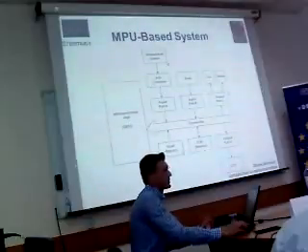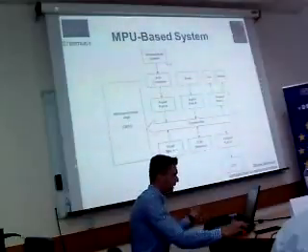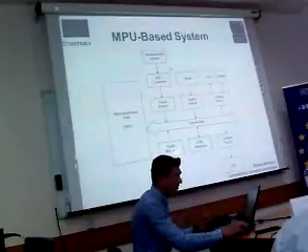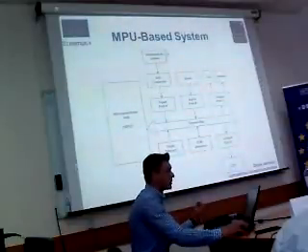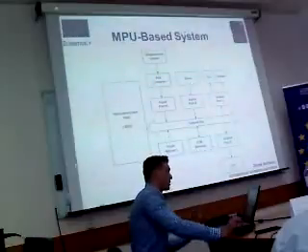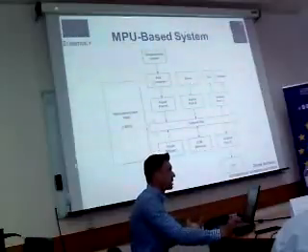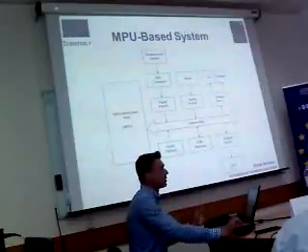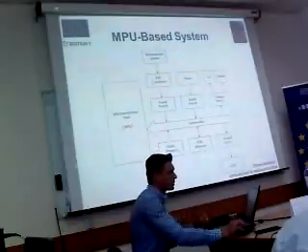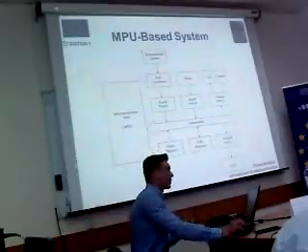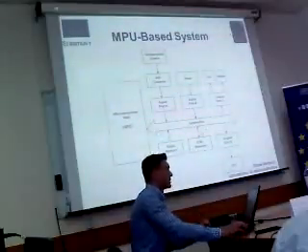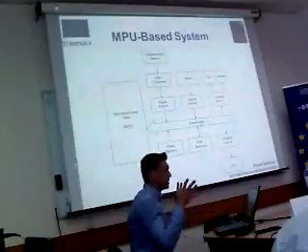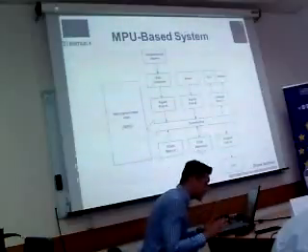What a temperature sensor does, you know, yeah? It measures the temperature, and this temperature is translated to an analog voltage change. So the higher the temperature, the higher the voltage, for example. Then this analog voltage signal goes to the converter, and then we can convert it to a digital signal and put it into our system as digits.